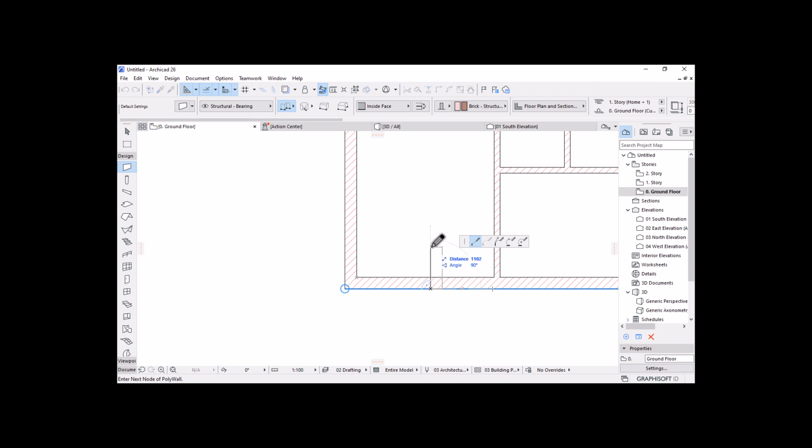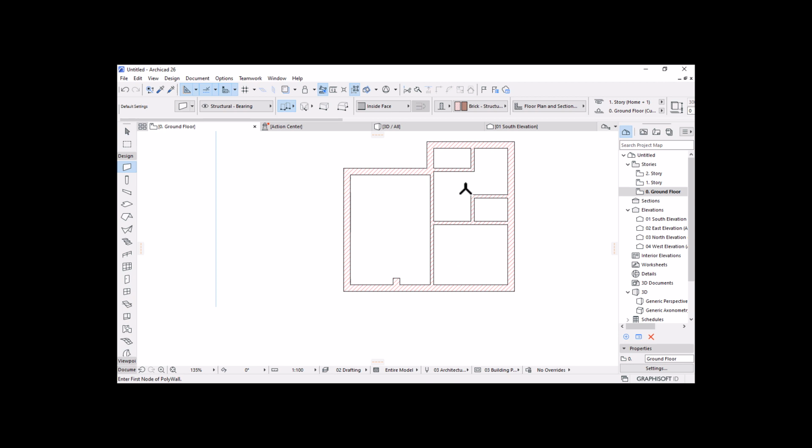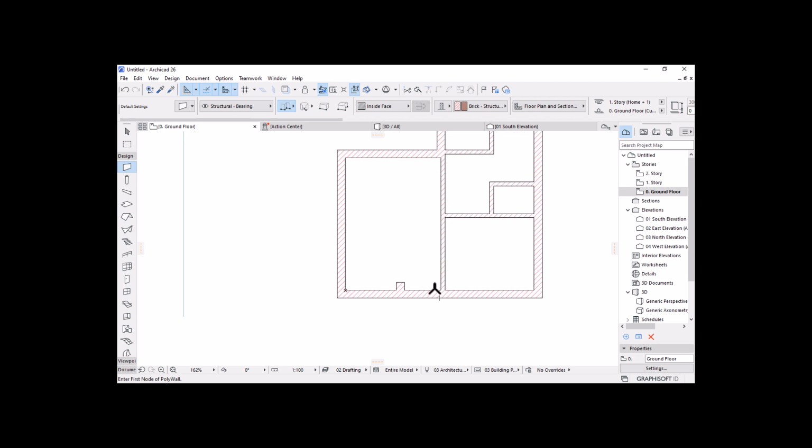This will go up by, let's say, 600. Right click and then hit OK. I still believe the distance between, let's confirm first the distance. I'm not sure this is what I wanted. I'll hit M like I said to measure, and this is 2.2. This is supposed to be 7 meters. 7 meters. Okay, I think it's fine.